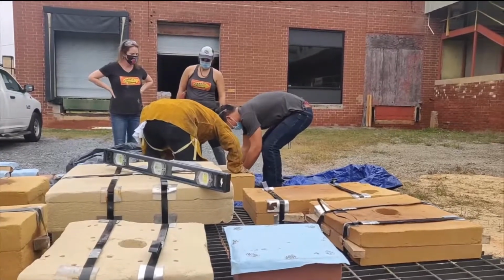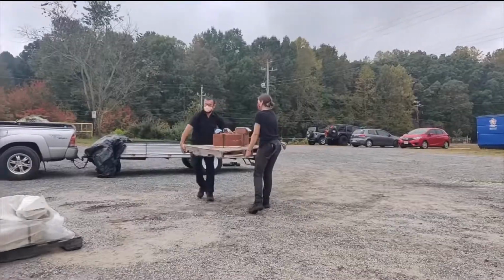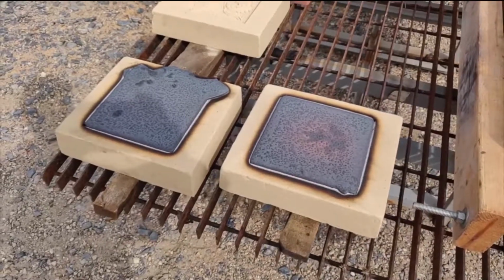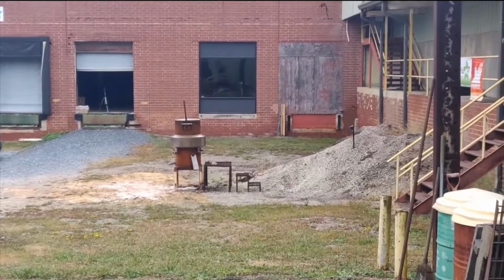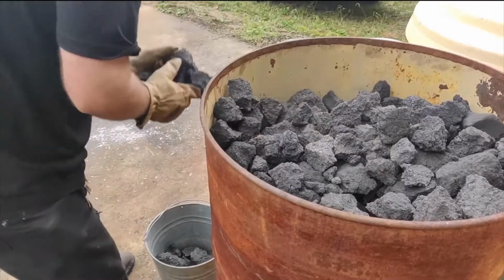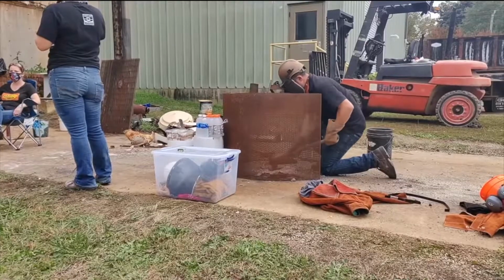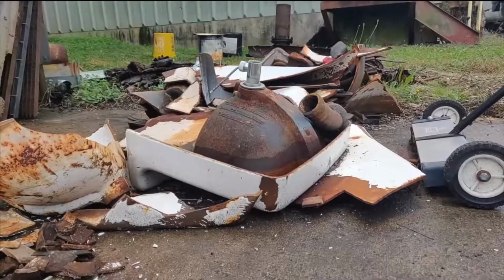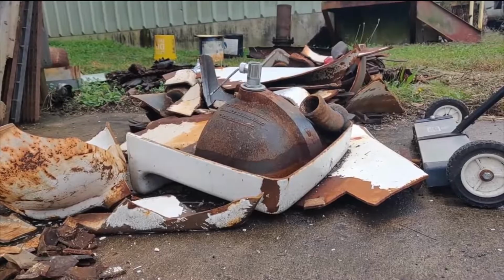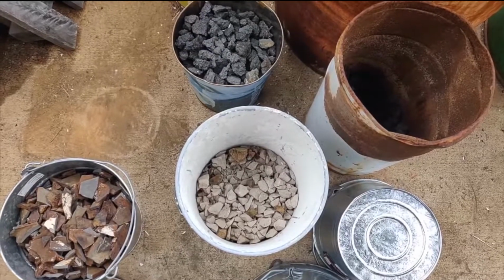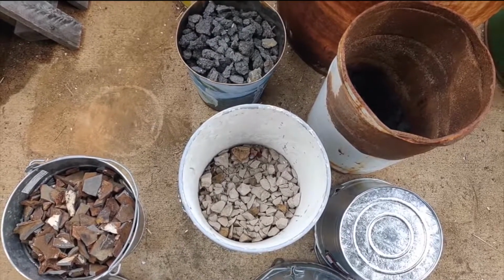Molds are made of sand and resin, and there are two types, closed and open-faced. The days leading up to the pour consist mostly of cleaning the furnace, breaking the coke, which is the fuel, and breaking the iron. Iron usually comes into a pour in the form of scraps, which they then make smaller into palm-sized pieces, or like little rocks.